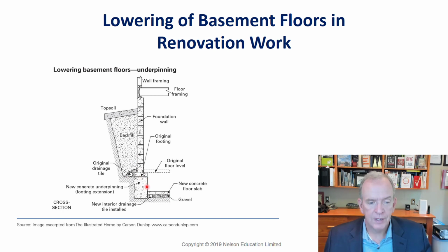But you don't have to excavate underneath. The downside of that is you lose all of that space, right? So you lose all of that space on the interior. So as much as it's cheaper, if you're going that far with it, generally on a residential application, it's worthwhile to actually underpin the house because it gains you so much more effective floor space.